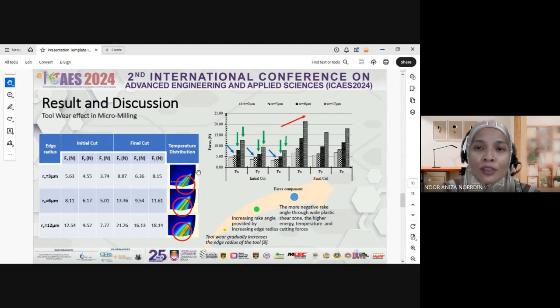Okay, this was the same as what occurs in the real machining process, where the contact temperature is the leading factor of the tool wear at the cutting zone. It can be seen that the temperature distribution contour was not located at the tool tip, but stayed above it, and can also be detected near the rake face of the tool rather than the flank face of the tool, as shown in these three figures.